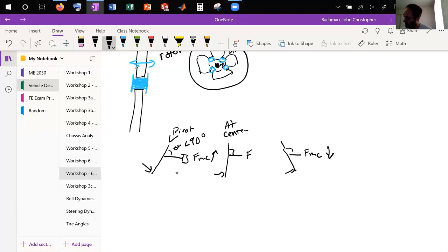Here it's kind of equal, and then as it goes past, let's say force of the foot is just constant in this case. And this is over center. What basically happens is the force on your master cylinder will start to decrease at this point, and so your driver will push harder and harder on the pedal, and they'll actually get less braking force, which is kind of a scary thing.